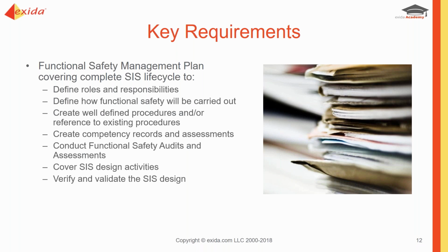And here again, we might be using independent third parties. There is a requirement to make sure that we have sufficient independence when it comes to conducting functional safety assessments and audits, but also doing validation. And then we have to measure performance. Remember, 61511 is a performance-based standard.